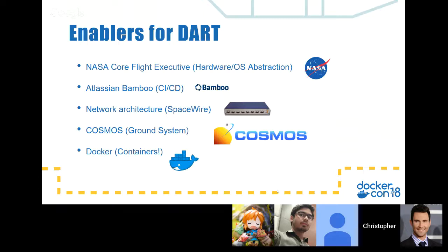So previously, most spacecraft have a processor in the middle. It looks very much like an embedded system. So you have a processor in the middle, and you have UARTs, or you have SPI, or you have direct links, GPIO, for example, that are all linked out to the specific components. And that's really, really hard to model without having the real hardware, because then you have to emulate every single one of those different links. Because we moved to SpaceWire, those links now look a lot like UDP.